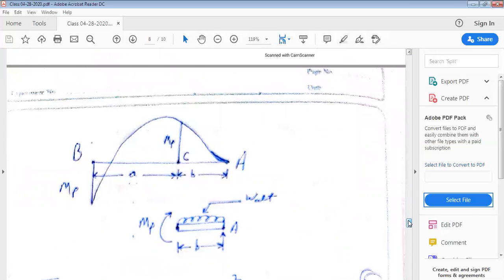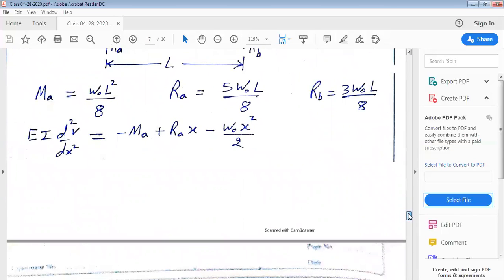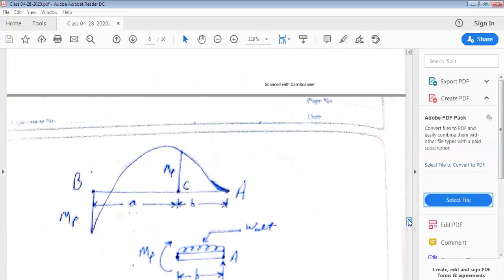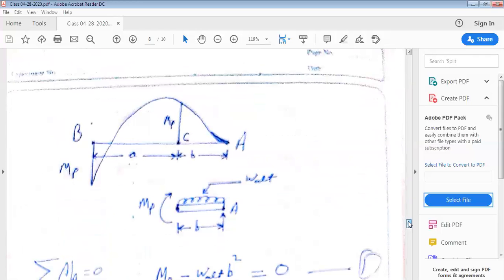Now this is the bending moment diagram corresponding to this nonlinear second order quadratic equation of the bending moment. At x equal to 0, the bending moment is minus MP, and at x equal to A, let us assume that we will develop a plastic hinge. So I'm drawing a free body diagram of the beam part of length B from the right end, which is experiencing a uniformly distributed load of W, and on the left end it is experiencing a plastic moment MP.